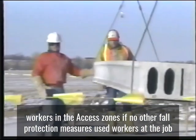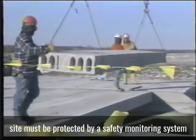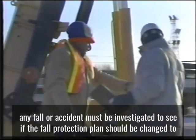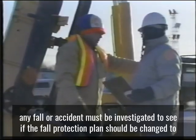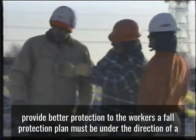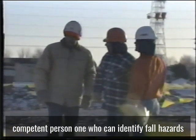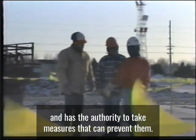If no other fall protection measure is used, workers at the job site must be protected by a safety monitoring system. Any fall or accident must be investigated to see if the fall protection plan should be changed to provide better protection to the workers. A fall protection plan must be under the direction of a competent person, one who can identify fall hazards and has the authority to take measures that can prevent them.